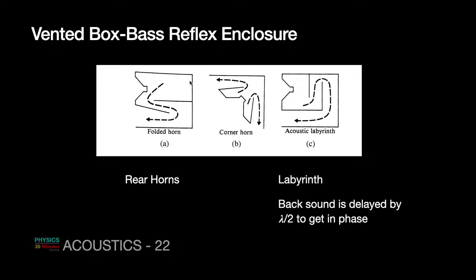So instead of just creating a vent, you first create a tube. The length of the tube creates a resonance mechanism. The tube undergoes resonance and that enhances the sound quality or sound output. The length of the tube varies from designer to designer, company to company, or speaker to speaker.